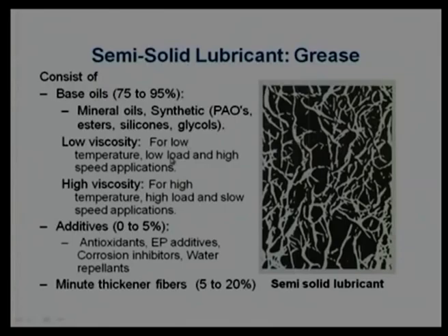And this kind of low viscosity oil can be utilized in low load and high speed applications. High speed application is emphasized here because in high speed applications there will be more and more shearing. If there is more shearing, more friction means more heat generation, the temperature will be high, and then the viscosity will turn out to be low anyway if we use a very high viscosity. So, there will not be much effect of using high viscosity except losing energy.